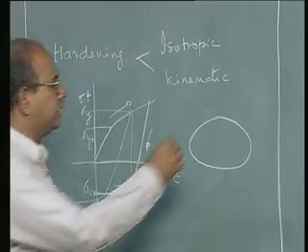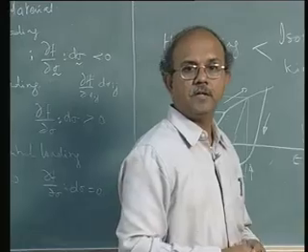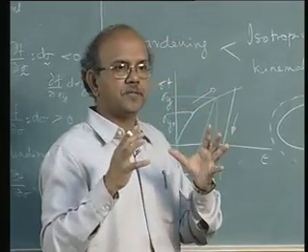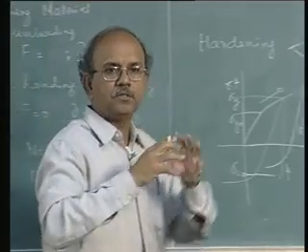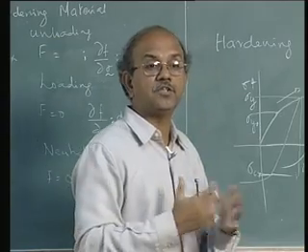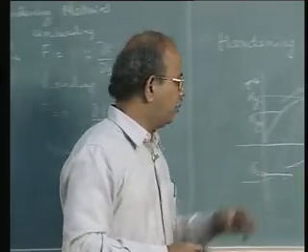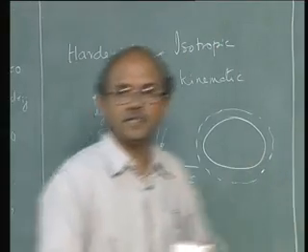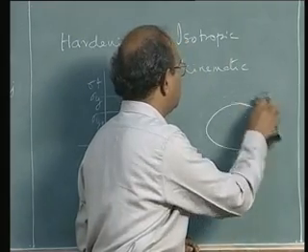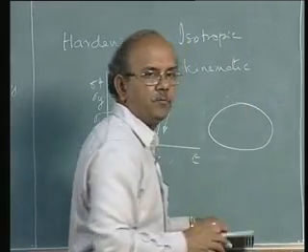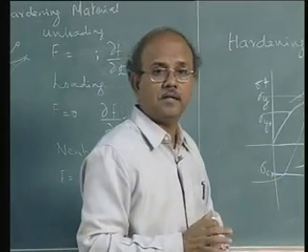One we already saw yesterday, that this yield surface may keep dilating like blowing a balloon, okay, it keeps dilating. So, if you are sitting here, you will move as if you are sitting on the balloon, okay, you will keep dilating. This is isotropic hardening, right. Now, forget for a moment that there is isotropic hardening, right. So, remove this. Of course, materials have both kinematic and isotropic hardening acting together. Most of the time it happens like that.